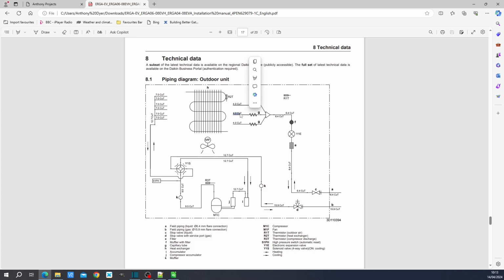So you will have therefore an unstable vacuum pressure here, and then that in turn affects the discharge pressure from the compressor, which your expansion valve is reacting to. And also your current draw for the compressor will react to that. So all told, low outputs create unstable conditions, and sometimes they create stubbornly inefficient conditions here.